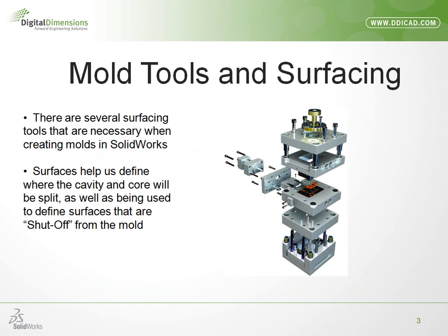But like I mentioned a moment ago, there's definitely a correlation between the mold tools that I'll be using and surfacing tools. That's not to say that I can't create a surface model that has nothing to do with the mold. It's just that a lot of the common mold making techniques involve surfaces. In fact, when I go over these automated tools in the mold tools toolbar, you'll notice there are a lot of very specific surfacing commands that are necessary in order for me to get my mold. One example at the top of my mind is just the parting surface. The parting surface defines where the core and cavity will be split from the model. So it's definitely a very useful tool, but there are other shutoff surfaces and just the common techniques when working with a lot of imported bodies as well.